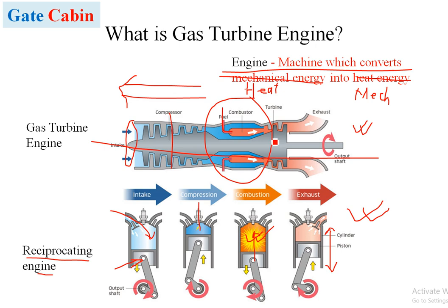The first and most important thing: the compressor and the turbine are connected here. So the turbine starts rotating. When the turbine starts rotating, the high temperature gas produces energy sufficient enough to rotate this compressor, because it has to produce very high pressure. When we start compressing air, the air will start producing resistance. So you need to have more and more power. So this turbine has to provide sufficient power or rotation speed so that we will be able to reach a certain designed pressure ratio.